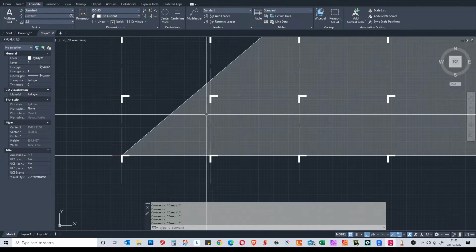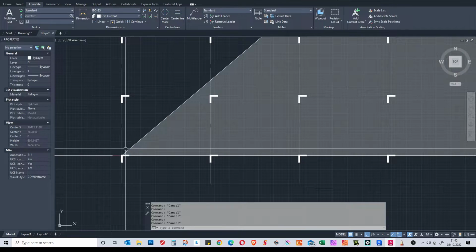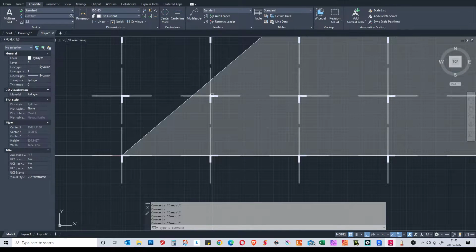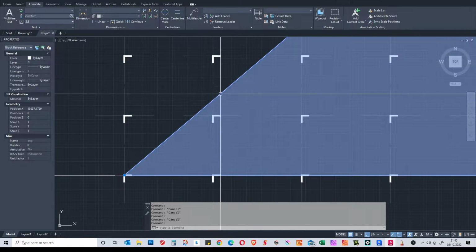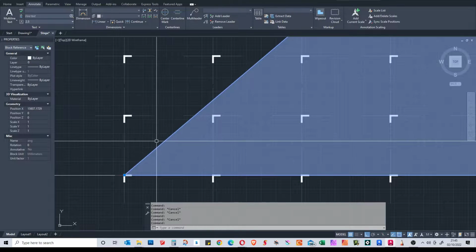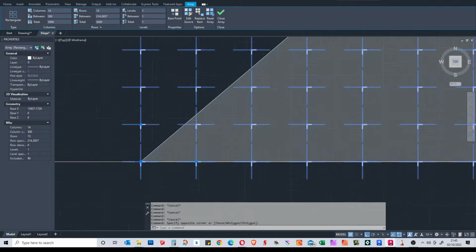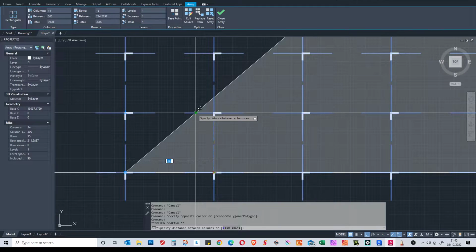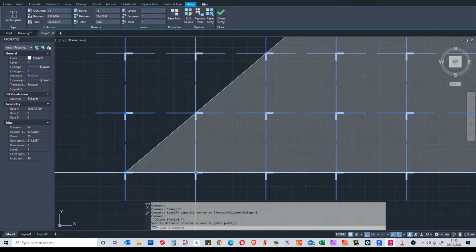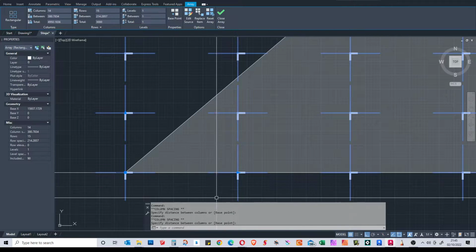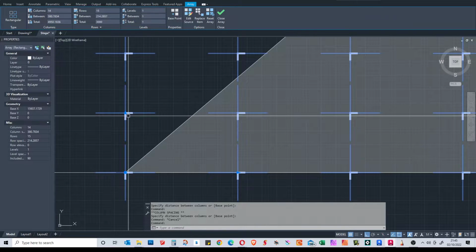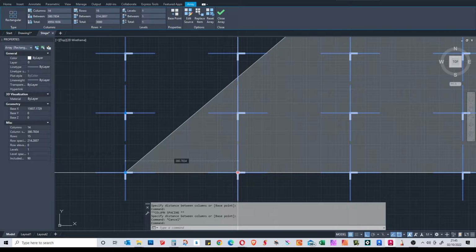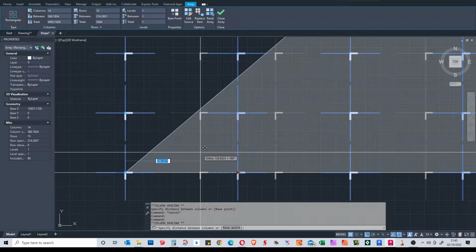Now what this does, if you imagine that is 1 step, you see, and so we know that this is our 42-degree line. All we have to do is pick this up, and as we've got the array set, put that on that intersection. We don't have to do any maths, it just moves. I'll just show that again. I'll move it across. There's a little arrow here, so as soon as you click the array, I've clicked off the array. Click there, you've got 1 arrow here, we don't touch that one. This is for the columns. You've got an arrow here. We click that and we just move it back.